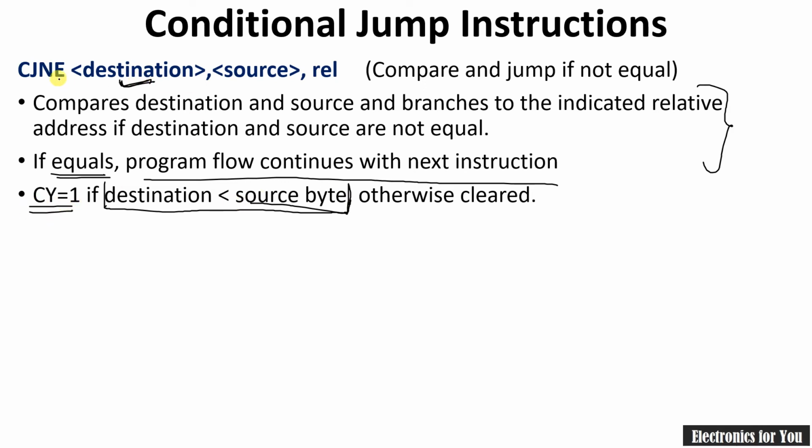It means that if the carry flag is set, the source is definitely greater than the destination, otherwise it is cleared. If they are equal, the program continues with the next instruction. Also note that the destination and source bytes are not affected, they remain as they are; only the carry flag indicates whether the source byte or the destination byte is greater.